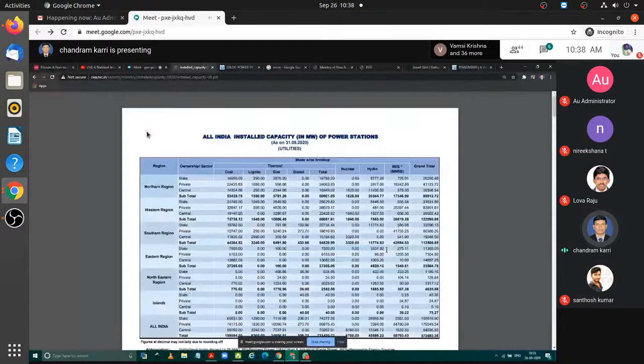If you are a power system engineer, I mean, if you know something about planning a power system, everybody knows for planning a power system, we go for load flow studies. So when you apply load flow studies, your first constraint is whatever is assumed at the generation side, all generated powers must be constant. But when the renewable energy sources are integrated to the grid, then you have to reformulate entire operations of power system. So these are some difficulties we are facing in terms of power generation.